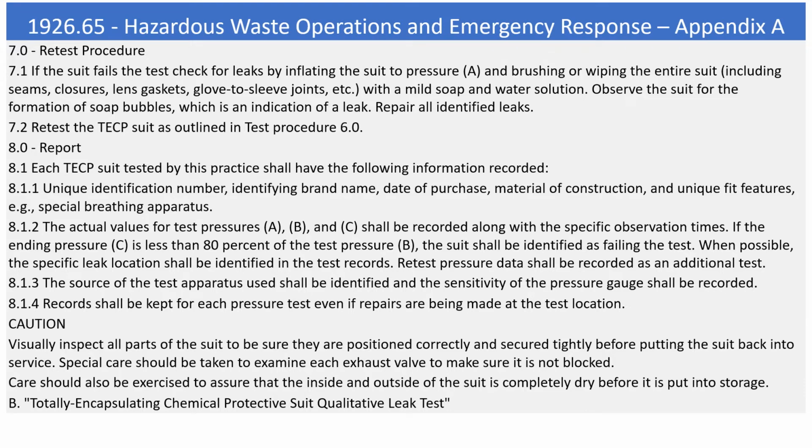8.1.3. The source of the test apparatus used shall be identified and the sensitivity of the pressure gauge shall be recorded. 8.1.4. Records shall be kept for each pressure test even if repairs are being made at the test location.